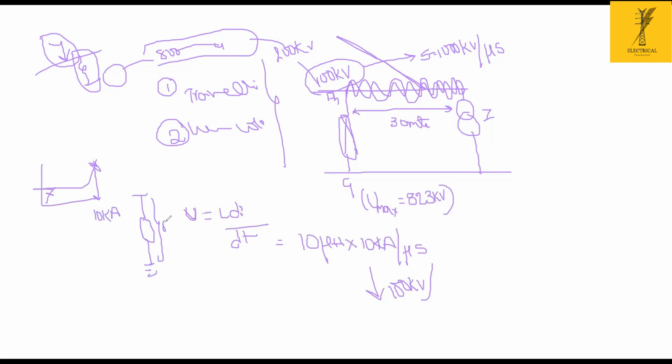Generally, we have to maintain the standard BIL level of my transformer relative to the lightning protection. So this 823 kV appears here with a 10 kA discharge current passing through. This 823 kV should be multiplied by 1.4, and that is equal to the standard BIL level of my lightning arrestor divided by 1.15, as a factor for non-self-restoring insulation. So that is the point. This 823 is nothing but the maximum residual voltage appearing at the discharge current of 10 kiloamps.